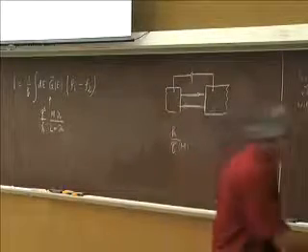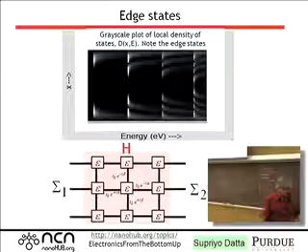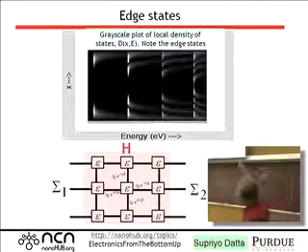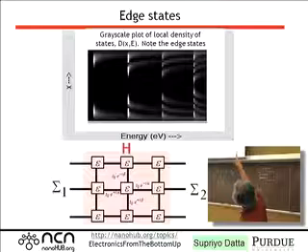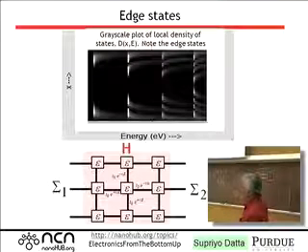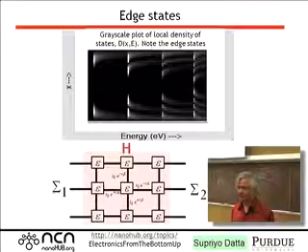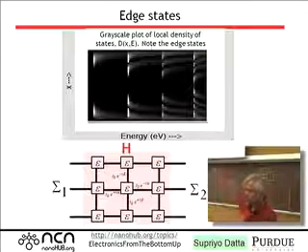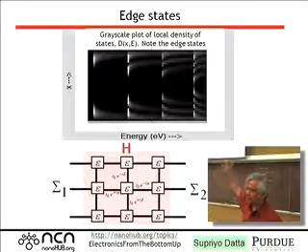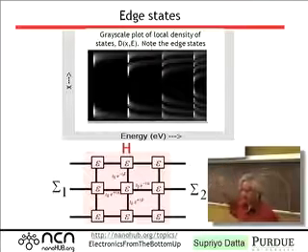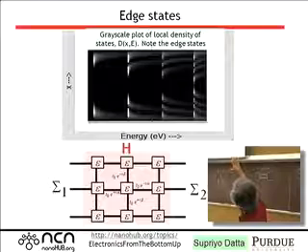and actually plot out what the density of states is at different points in the sample. So for example, here I've shown a calculation at high magnetic fields. What is over there is this grayscale plot. This axis is energy. That axis is the width of the conductor. And if you see a white spot, it means there's a lot of states there, high density of states. So what you're seeing is the spatial distribution of the density of states. How was this calculated? Again, with NEGF, you put in H, sigma, etc., and using those equations, you calculate it.